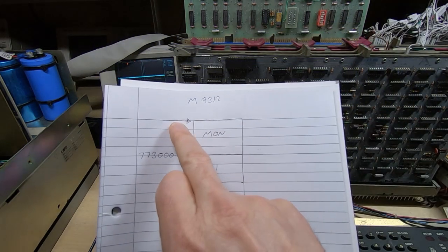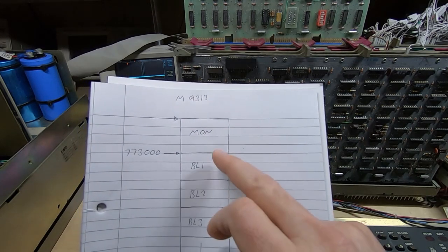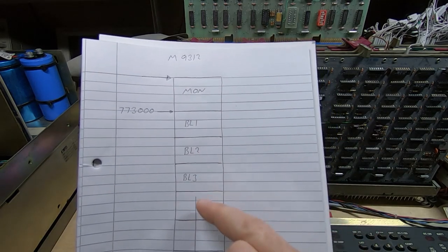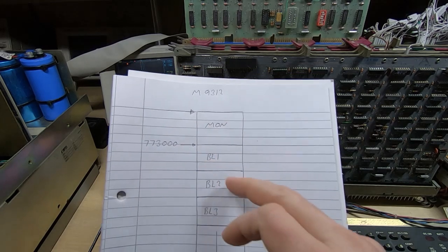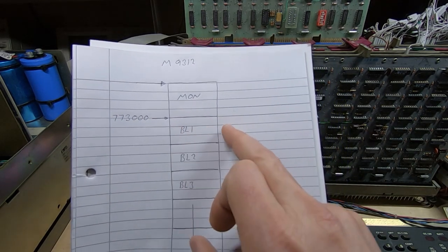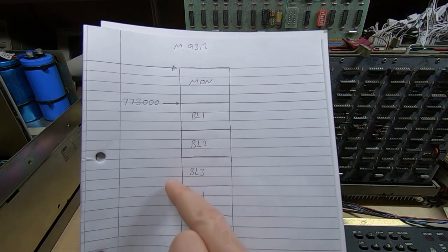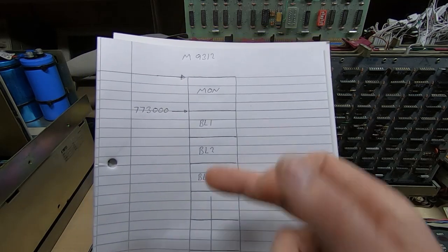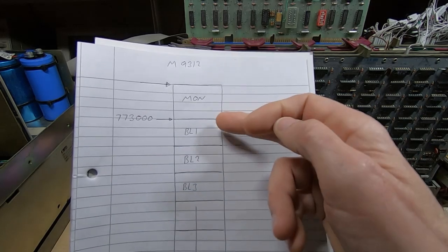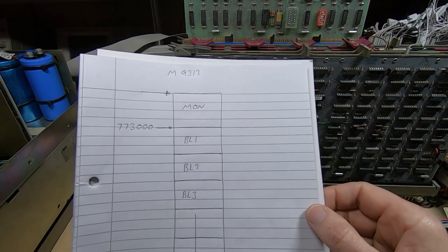So you have the start of the monitor program in effect, and diagnostics. That ROM is pretty much always there, and then you have the optional ROMs to use to bootload your specific hardware. You start with the first bootloader. You can put up to 2 images in each PROM, but effectively they daisy chain their addresses, and as you add them, the address moves down, and each one's identified by a 2-character code that you can trigger from the remote terminal.